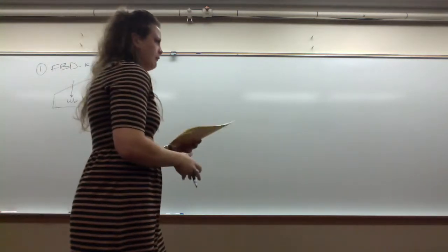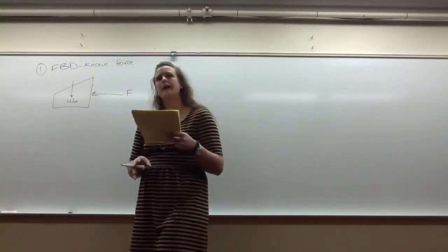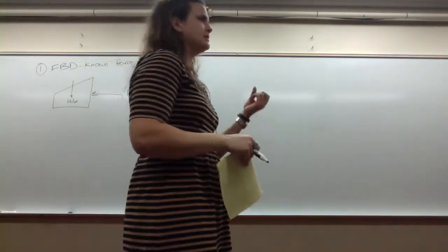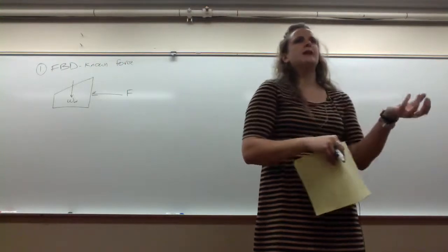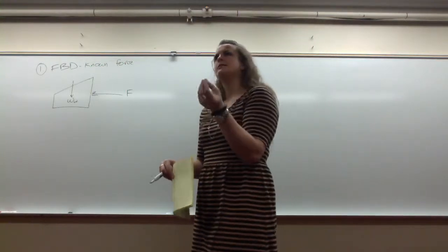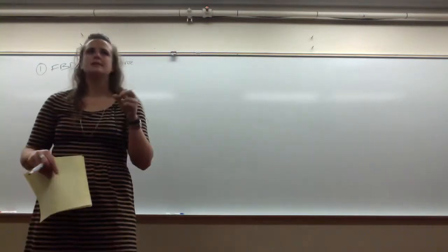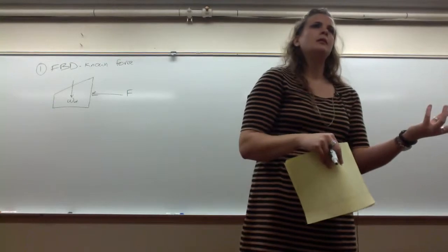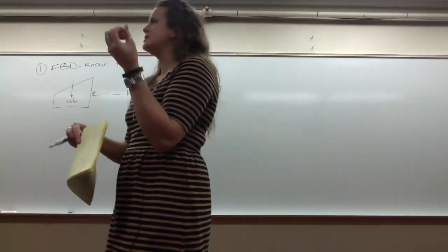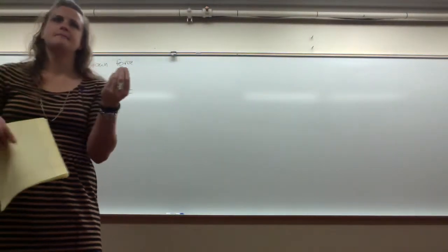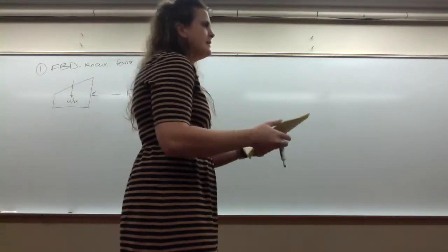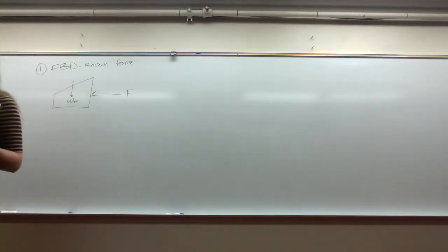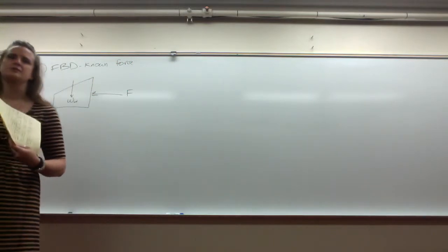And I want to stop here and back up a little bit from what I said on Friday when I told you that in statics the direction of friction doesn't matter. It only matters in dynamics. That's still true, but when analyzing wedges in simple machines, you need to take into account the dynamics of the system. So with simple machines, the direction of your friction force matters. And that is because the direction of impending motion will affect the friction force because friction does what?